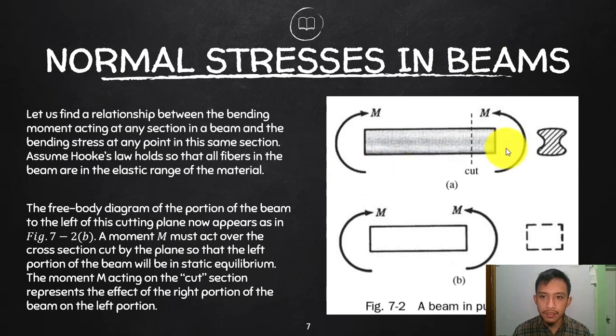You can read about this. Consider this one. For us to understand flexural stress, let's consider this beam. If this is a beam, or a member under a certain moment on both ends, then of course the member itself is under a bending moment, let's say M. If I cut at any section, that will be under a moment M. So let's say I cut at that cross section.